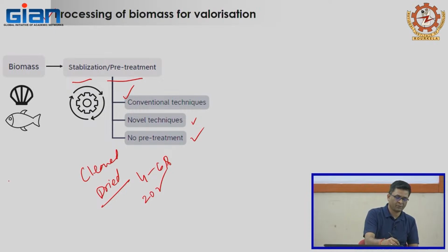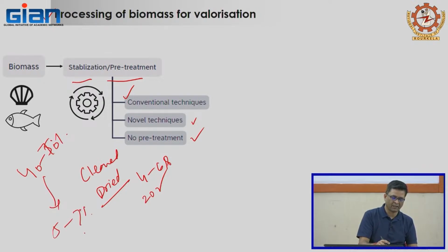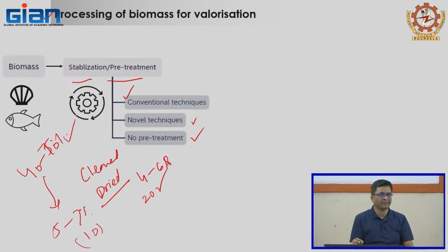Now, shells which were recovered might be having around 40 to 70% moisture. Shells were dried to 5 to 7% or up to 10%. Then you are adding 1:20 water. If you use fresh shells directly, which will be difficult to crush, then you do not have to use 1:20. Here what you are doing, you are removing the water, then you are adding the water.